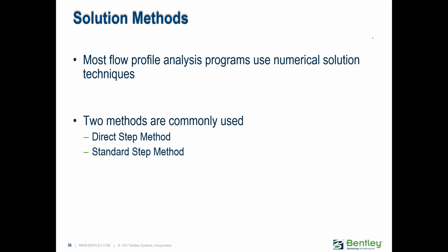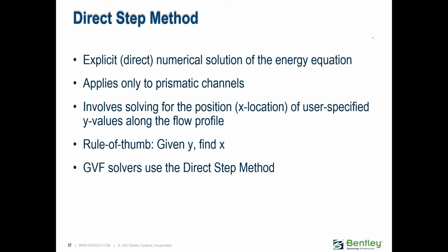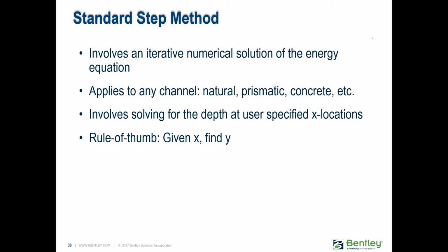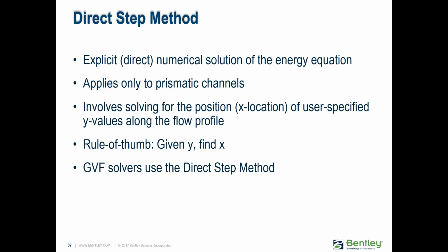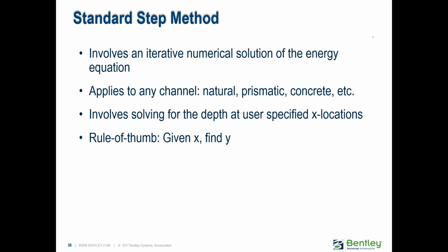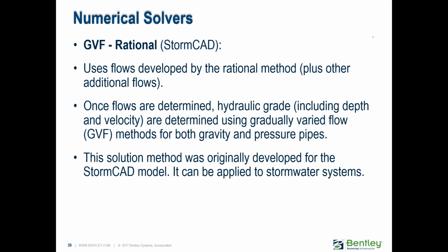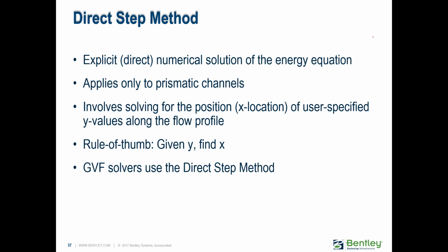So knowing all this, conservation of mass and conservation of energy, how does the software come up with the solutions? Well, there's the direct step method and the standard step method. Both of them basically involve dividing the channel into little segments and then solving for either depth or length of the segment. The direct step method assumes a depth and then solves for the length of the segment, whereas the standard step is the opposite. It knows the lengths and it solves for the depths. The StormCAD solver uses the direct step method.